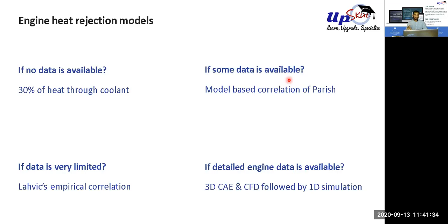If a 1D simulation takes maybe 30 minutes, the same amount of work on an actual CFD will take, on our system, never, it will never end. On a very high end system it will take weeks. So it's not possible to wait for 1 week for a simple change. That's why we do 1D simulation. 1D simulation has some errors, that's why we need to calibrate them. We're going to discuss that also.